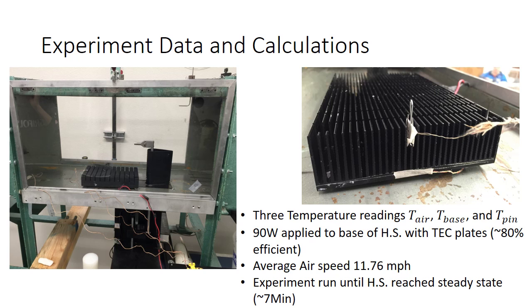but as you can see, the surface of the interior of these fins are rugged. They have sort of little waves on them to give them more surface area and supposedly to help with convection. It also has another fin cut out in the transflow direction as well. So this is a fairly complicated geometry of this heatsink, and it'd be hard to model this with simple calculations like we normally can with typical straight pin heatsinks.